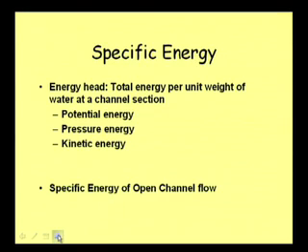So, energy per unit weight of fluid is called head, energy head. Now, when we write the expression for this energy head, you can concentrate on the slide. We can call the energy head the total energy per unit weight of water, and of course, fluid means in hydraulic engineering we talk about water at a channel section.